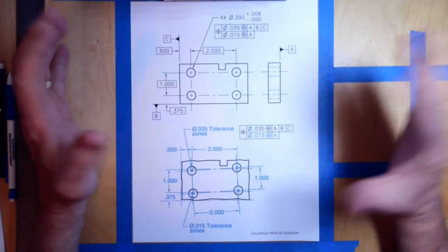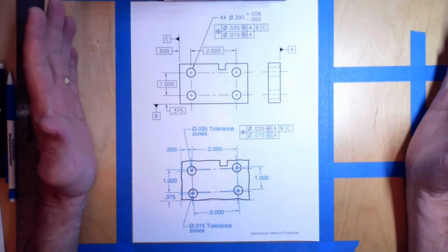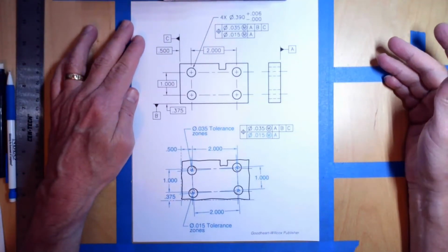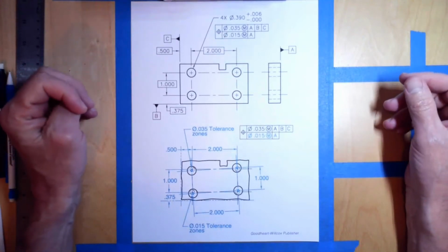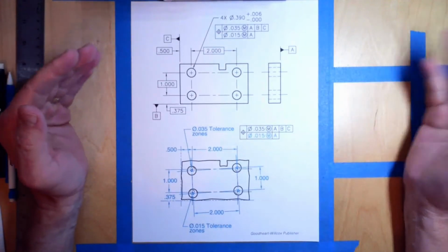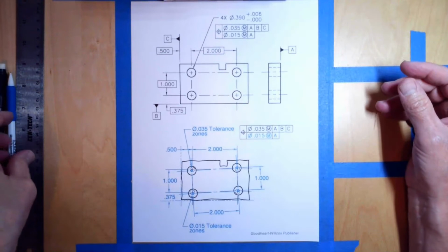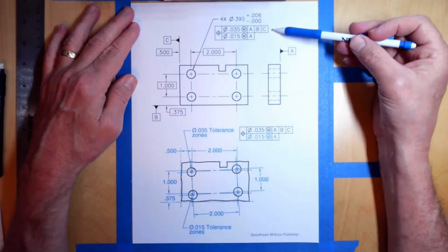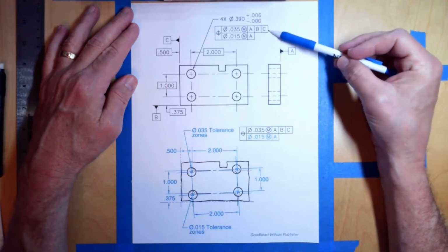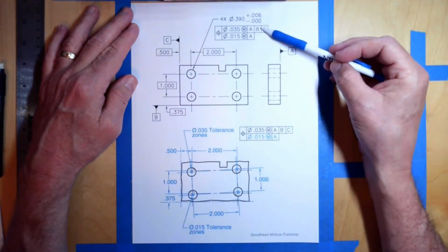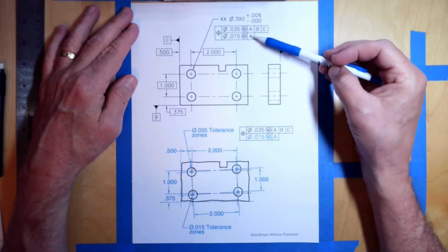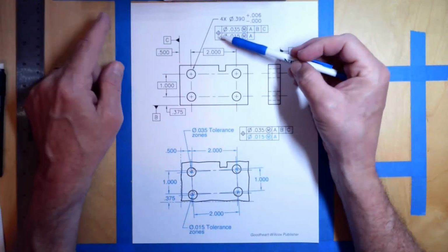Okay, so first of all, I'm also going to use figures from the book for the most part. I have one example that I want to do later that is not a figure from the book. But first of all, with composite positional tolerancing, what we're talking about is a dual feature control frame. So we have a two-segment feature control frame, the upper segment and the lower segment here.